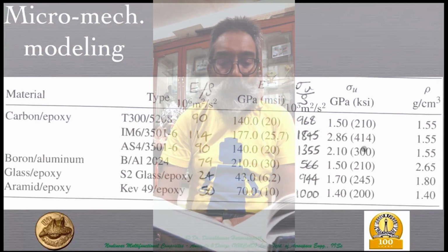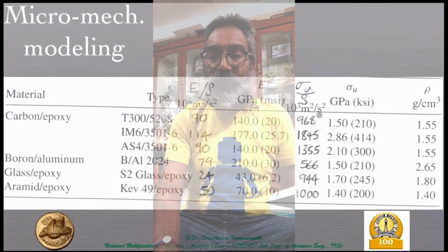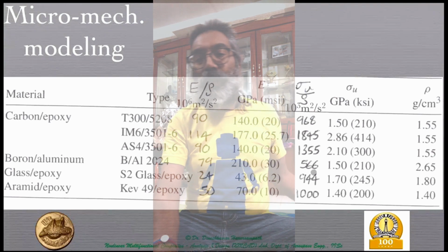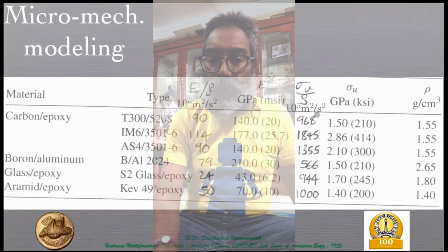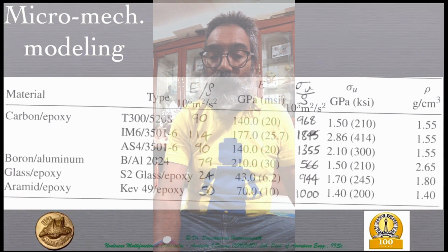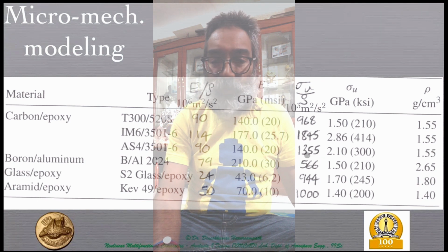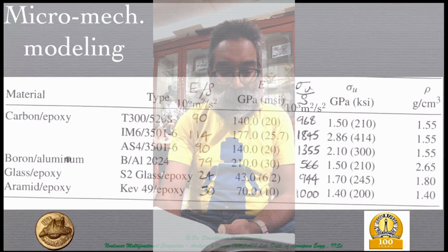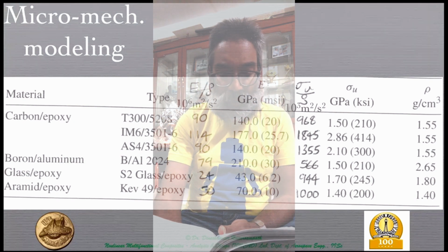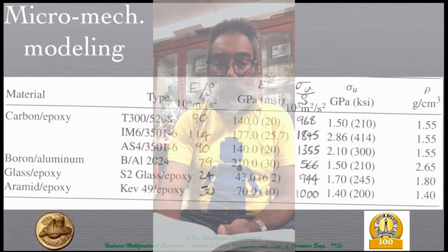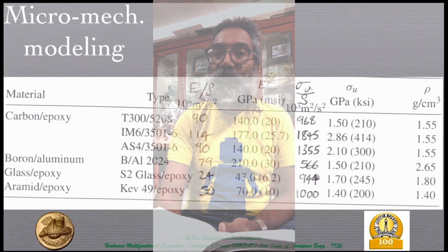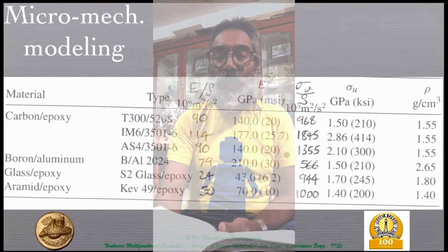So you'd see that in terms of the specific strength design, there's a big jump all the way from hundreds and 200s for the case of metals to all of the order of 1000. In this case it is smaller because it's a metal matrix, so it's kind of comparable. But even there, if you compare to a typical aluminium, which is 162 to 194 range, the introduction of the boron fiber has increased it about 2.5 times the original value.